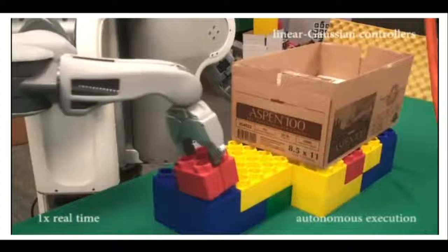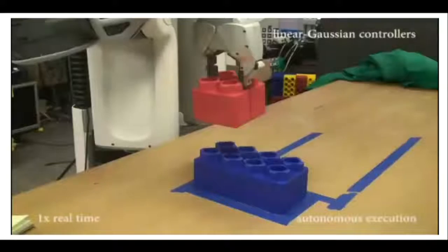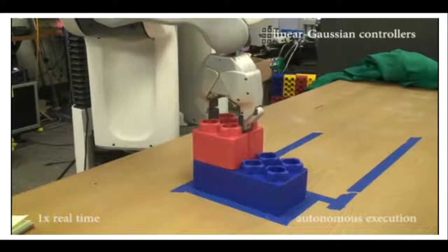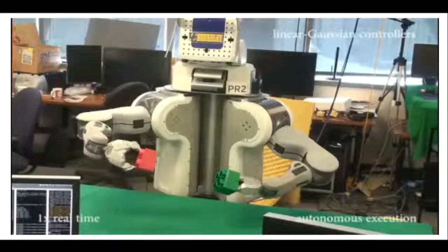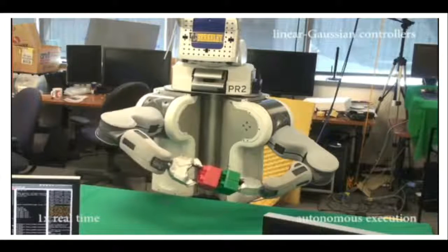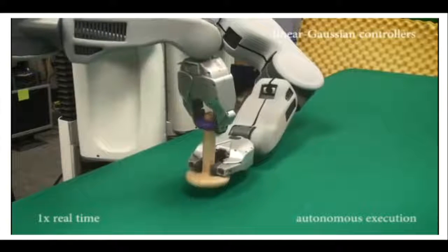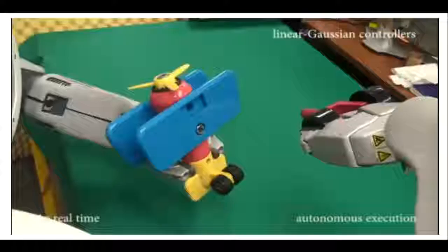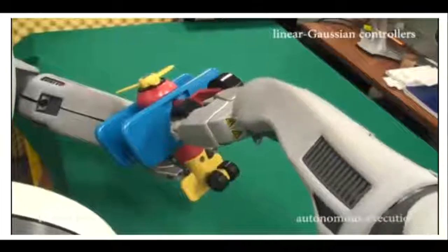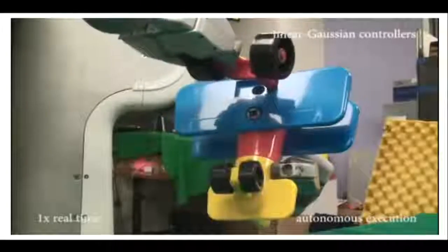Here's a video of a few trained controllers doing a number of different manipulation tasks. These are all trained using the same algorithm, just using the local model stuff. There's no deep learning at this stage. We'll talk about how to bring that in the next lecture. But for now, this is just showing the different unknown dynamics systems where this can work. The state space here is the positions of all the joint angles, as well as the end effector, and their time derivatives, their velocities. And the actions are just the torques on the robot's arm. So that's showing some of the results.